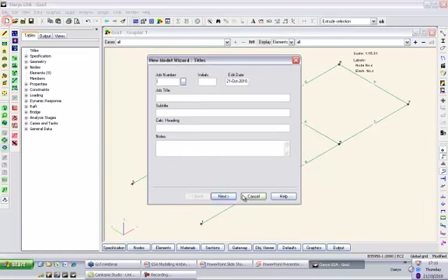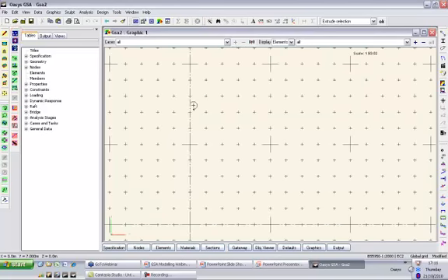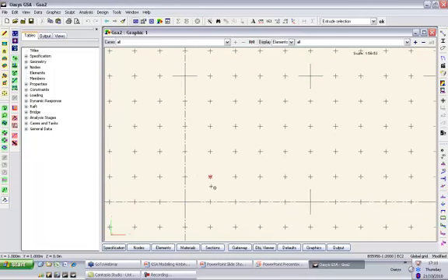Right, let me just bring up a new model and draw in the grid. Now, I mentioned this snap grid. One thing I didn't mention is, if you see, it's wanting to snap just to those intersections, which is fine. But if I turn snap to grid points off, you'll find it wants to go anywhere, and there's no real control over where they go.